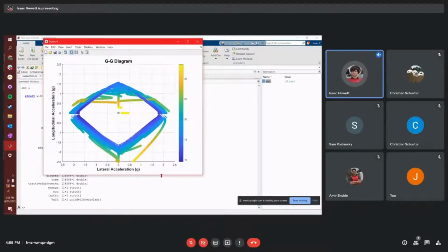This is the LapSim GG plot, which is a classic vehicle dynamics plot that we should be using and evaluating. This is how the LapSim interprets the results. You can see it's a lot more square, and that's because another limitation of the LapSim is we're not using accurate tire models. We're effectively always at the tractive limit of the tire, and it's a relatively simple tractive limit that's not varying with temperature. Something else we could improve on, if someone wanted to take it on, is implementing a more accurate tire model. And I actually have some links for that I've seen people do.